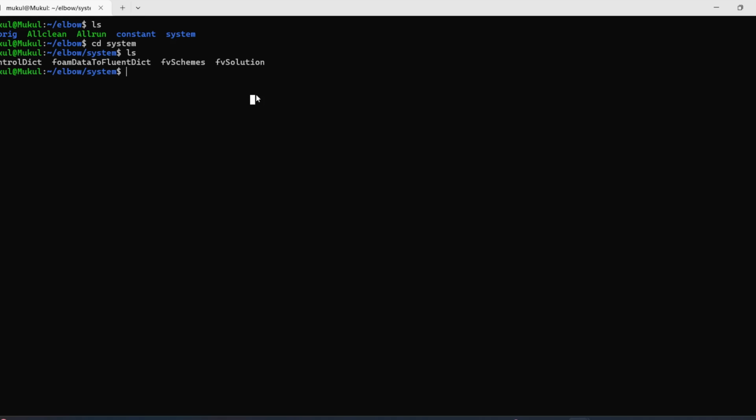In that case you can use this OpenFOAM approach which I am going to tell you. Just transfer the mesh here, run the solver, then again you can transfer the OpenFOAM data to ANSYS Fluent for post processing. Specifically for this, this process is being done.